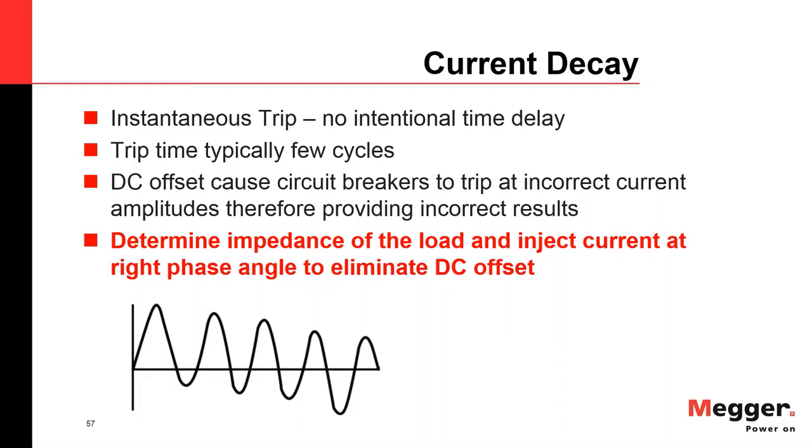What you have to do is the device that actually makes the current, closes the circuit, the gating device, you have to adjust the firing angle. And the way you do that, your current meter has to be able to measure true RMS, and it has to be able to measure what's called peak divided by square root of 2.